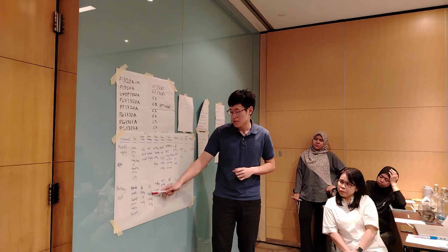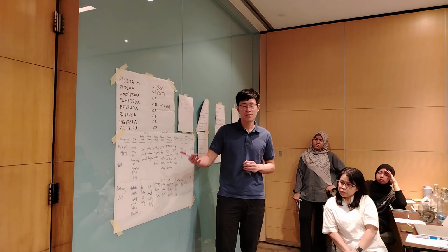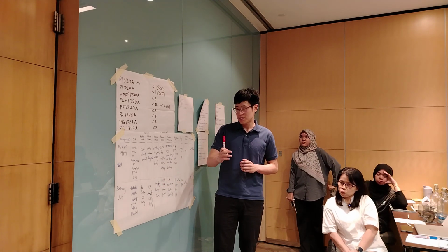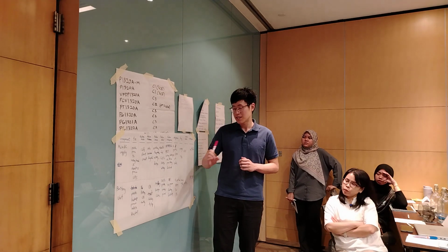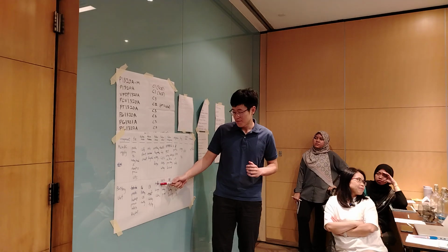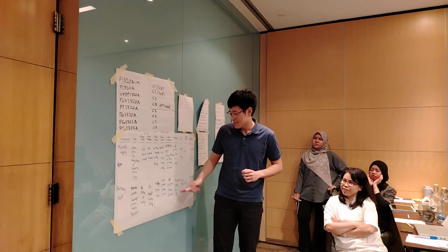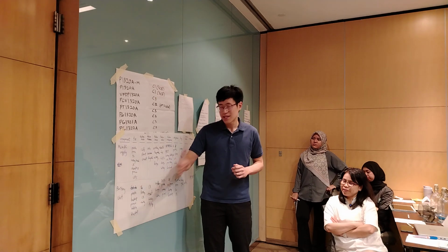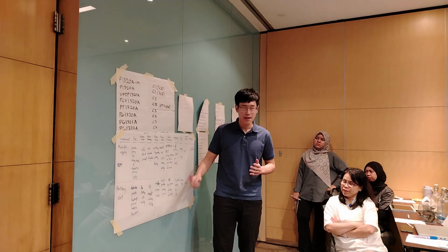So what can cause the circuit breaker to forcibly trip? Maybe due to aging or design factor. Maybe the circuit breaker specification is wrong, like the overcurrent rating is set falsely. Yeah, design failure. And the failure effect is, when the battery circuit breaker opens, it cannot provide power during blackout.